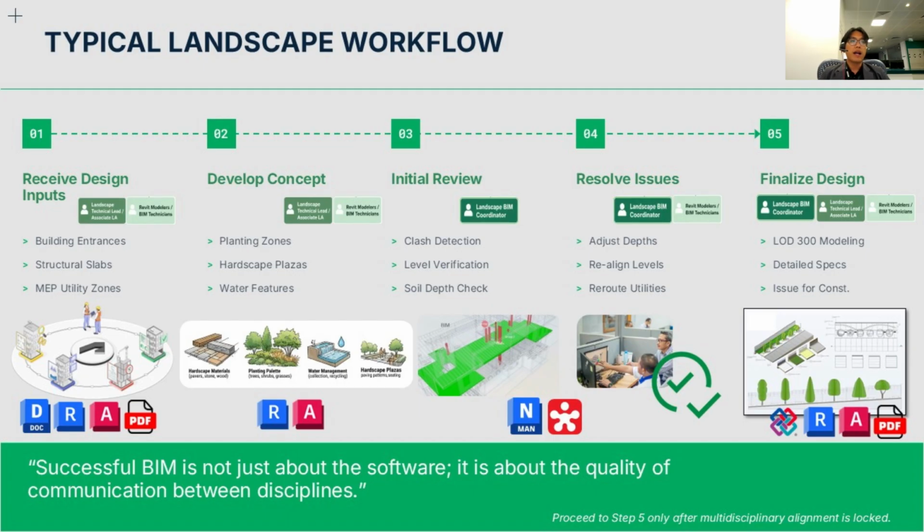The next step is to initiate the review. The review could be based on the 3D model or maybe just the 2D case. We can already do some coordination, like level verification or soil depth checking. Some information requires 3D coordination, so we need to use tools like Navisworks or Revizto.